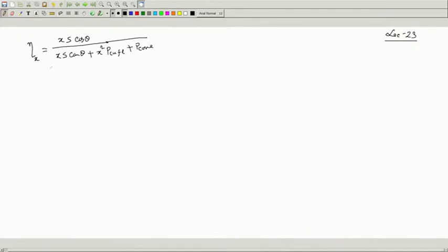And we found that the efficiency curve will be like this. This is some efficiency curve, and I must attach to each curve the power factor, cos theta equal to say 0.8. I showed last time that for a given kVA, this axis is x, the degree of loading, and this is your efficiency, and this is the value of x at which maximum efficiency occurs, P core by P copper full load.